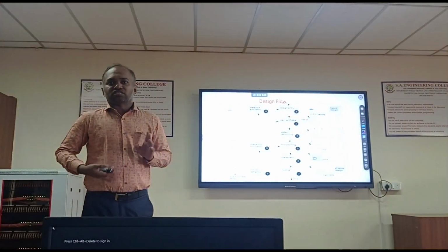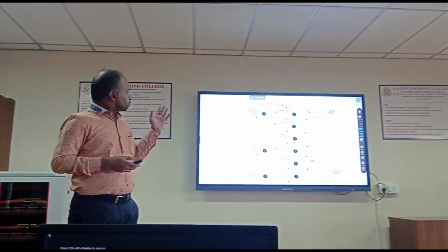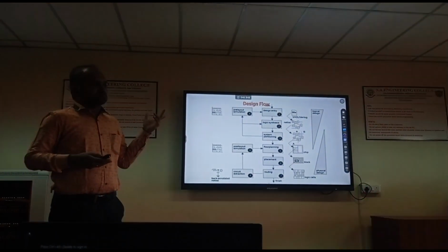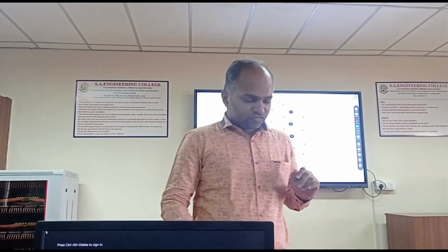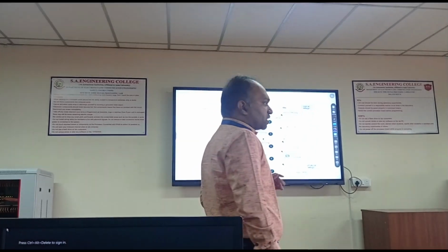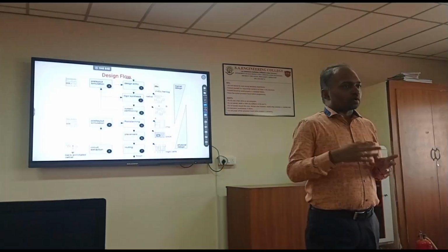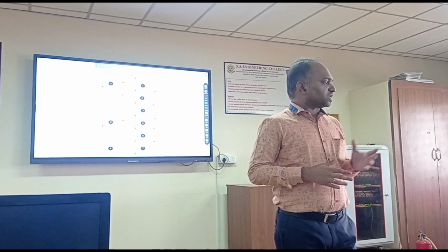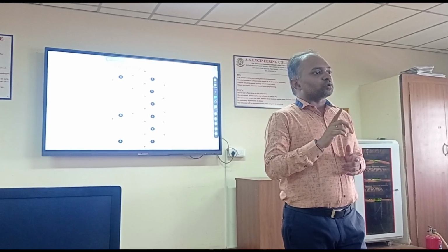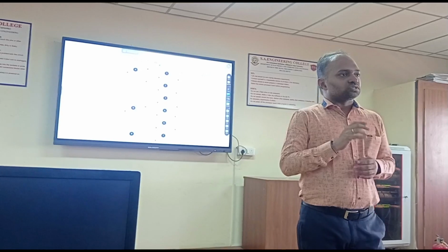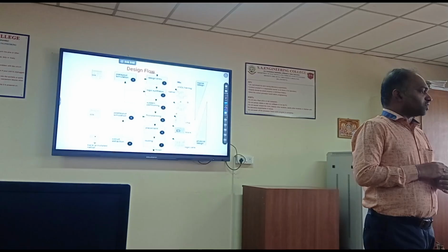I just wanted to touch on a few other things before going into the topics, because you will not be able to relate otherwise. You all might have heard about the design flow, right? What is a design flow? Basically, there are two parts in IC design: front-end design and back-end design. Generally, front-end design starts with writing an HDL program for some particular application, in languages like Verilog, SystemVerilog, or VHDL. There are two main processes in hardware description languages: logic simulation and logic synthesis. What is the use of logic simulation? Logic simulation is the functional or logical verification of the circuit.